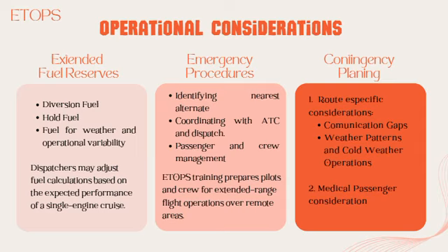And weather patterns and cold weather operations. Routes over polar or high altitude regions may encounter extreme weather, which can impact fuel burn rates, emergency descent planning, and the availability of alternates. Special attention is given to seasonal weather patterns, icing potential, and airport closures due to snow or extreme cold.